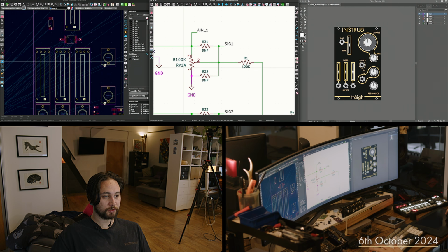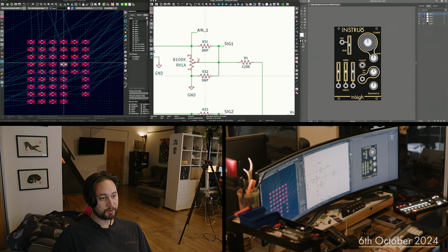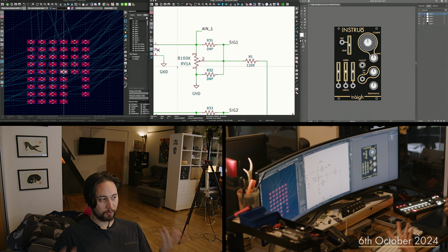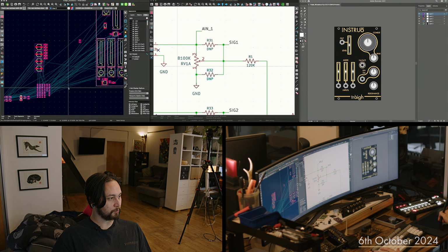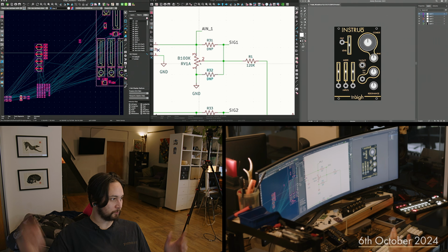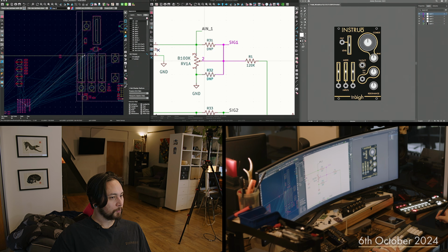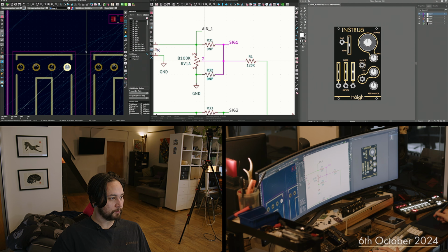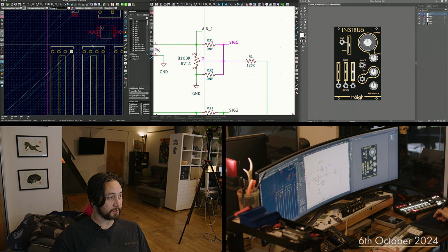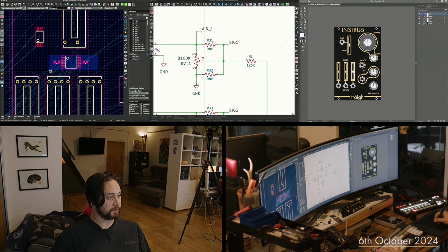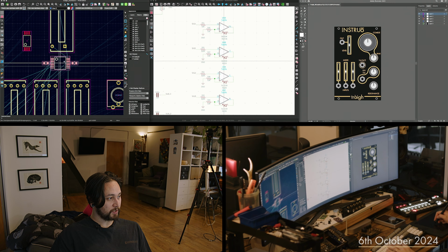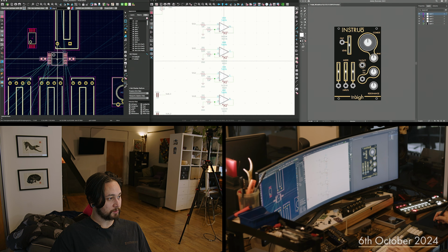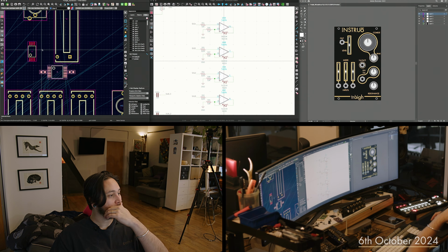So I've got these extra do not place 22k resistors, which are going to add the audio tapering, the log tapering or anti-log if I want, depending on, or tanh if I want. But it means I can put them close together too, so they're going to be top side here, which is quite easy to place, which means that might not be the best place for this TL074 if there's going to be resistors here that need to connect to this.